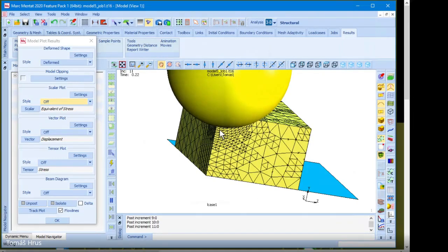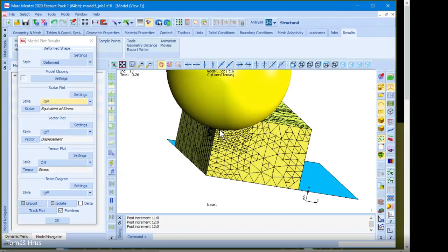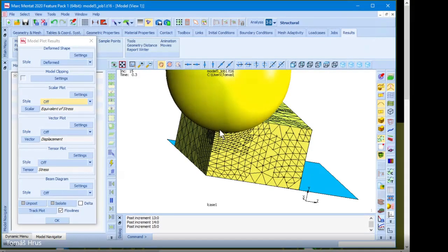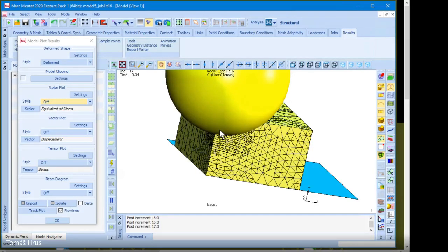So you have to find a compromise between the perfect mesh and a realistic mesh which works good enough for your purpose. Yeah. So I think the mesh adaptivity is a quite good thing. How to adapt? That means to increase the number of elements only in this part of the body, where it is important. Yeah. So the solution is going on.